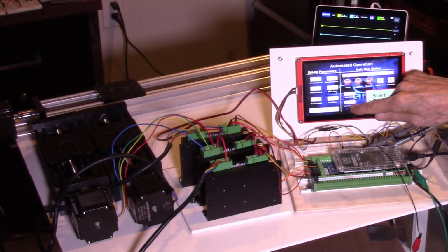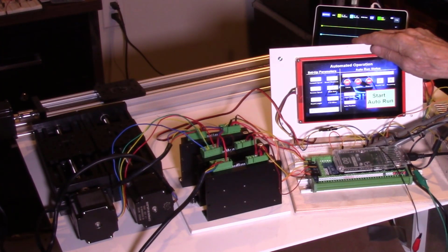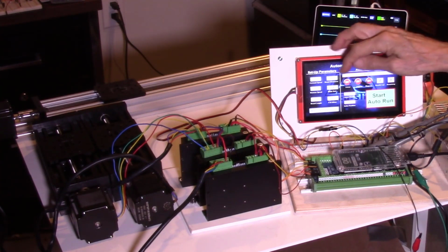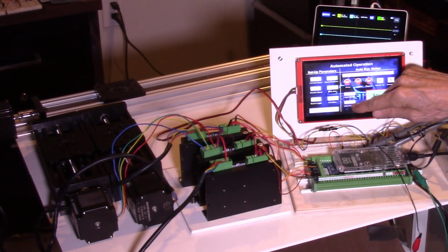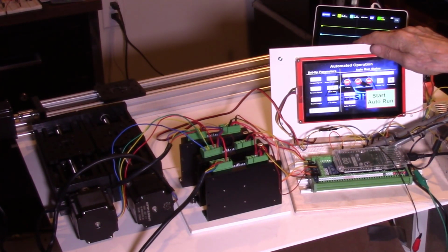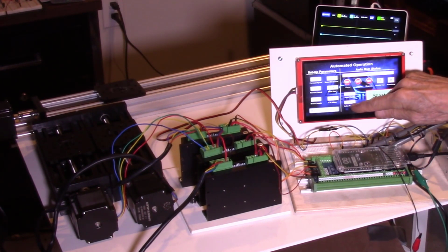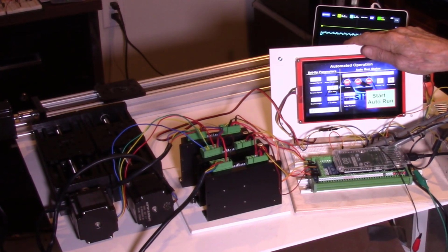This display is displayed in 3 digits, meaning thousandths of an inch. The Arduino software has limitations that it can only deal with integers. To get these displayed, I had to do a lot of tricks, but to get it here, I really can't do that. So I could have made it digits, but then when you went over an inch, it would create a problem. So I just left it as thousandths of an inch.